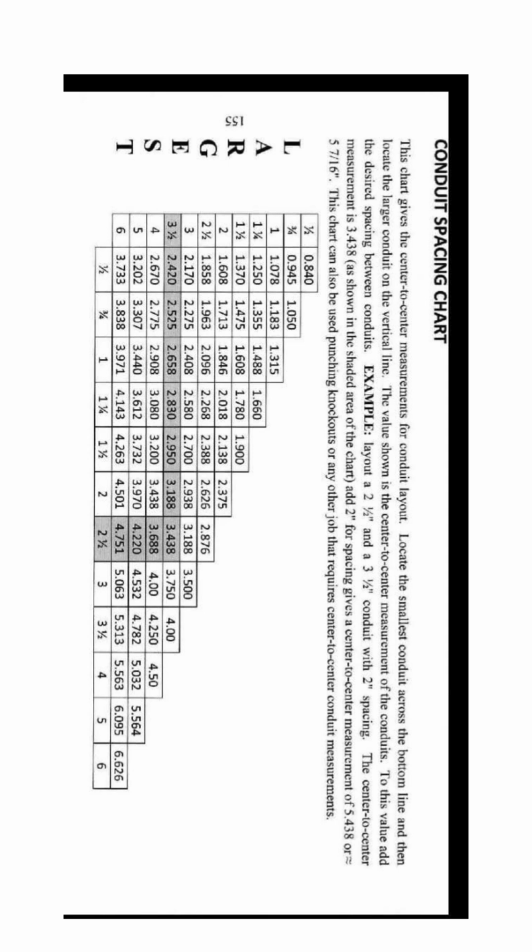Conduit spacing chart. This chart gives the center-to-center measurements for conduit layout. Locate the smallest conduit across the bottom line and then locate the larger conduit on the vertical line. The value shown is the center-to-center measurement of the conduits. To this value add the desired spacing between conduits.